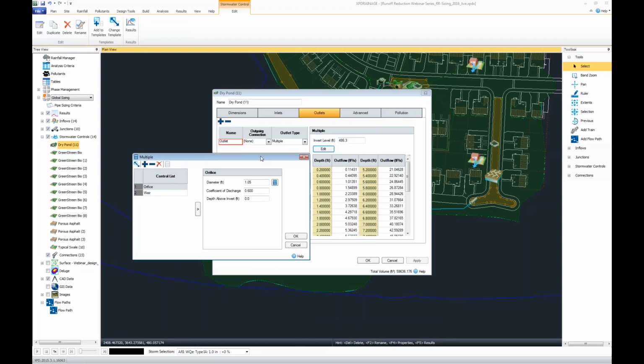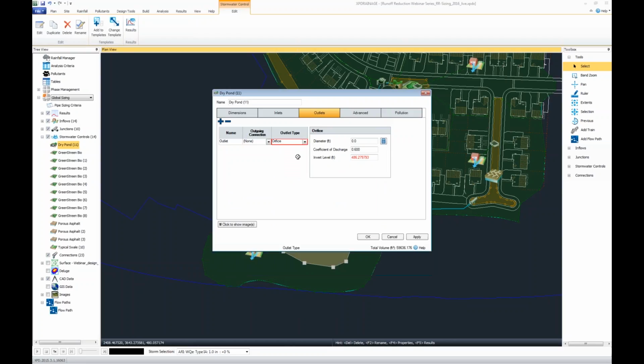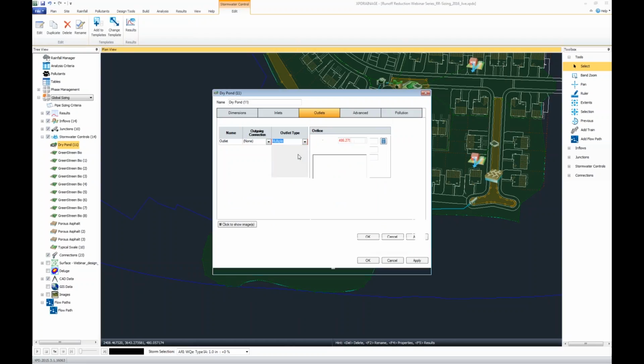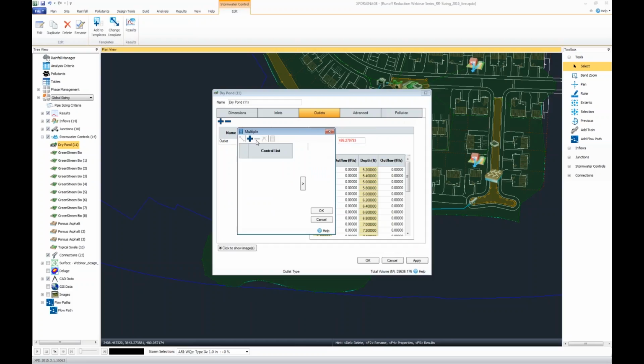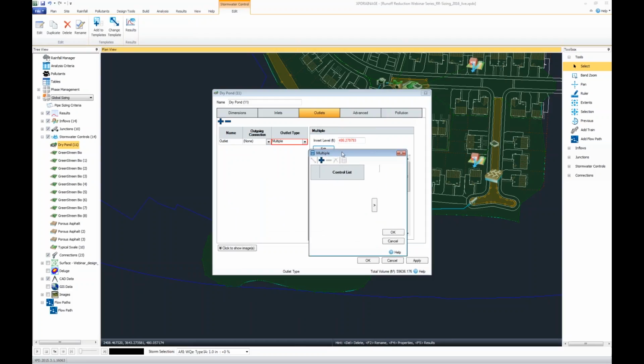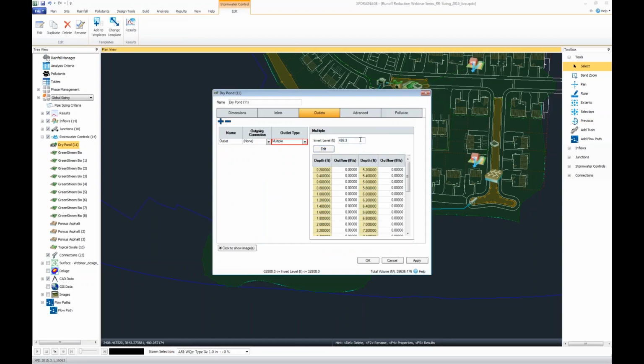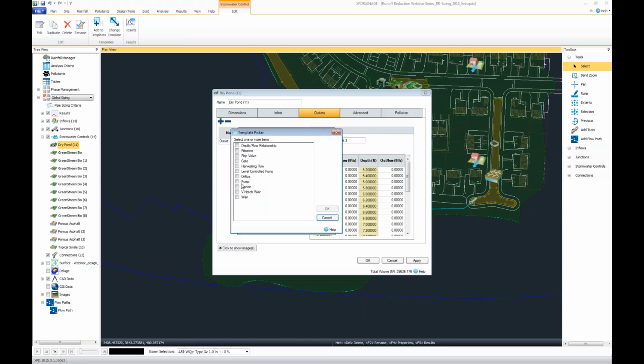So let's look at a multiple outlet type. I believe I might have showed this already last time. We have a range of different outfall configurations. Just a weir, just an orifice could be used. Okay, I want to look at multiple. So let's add this from scratch. And I'm going to say that we have, so I want a kind of low flow orifice and a weir.